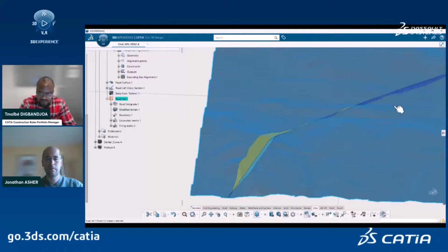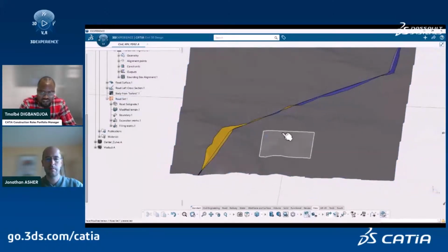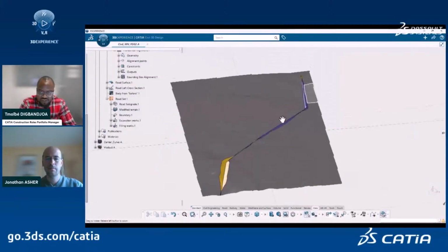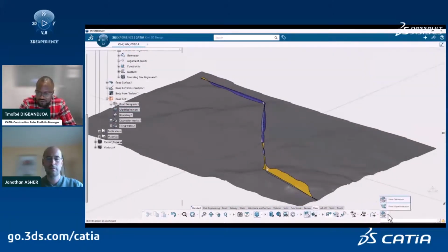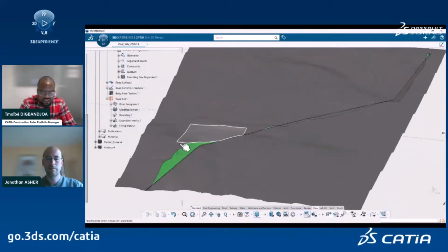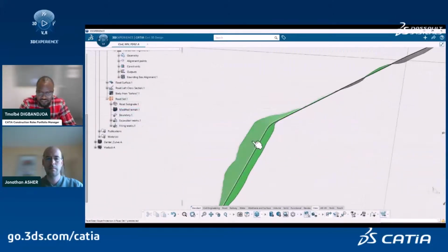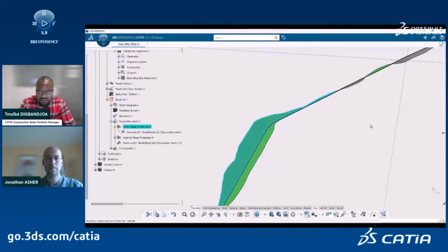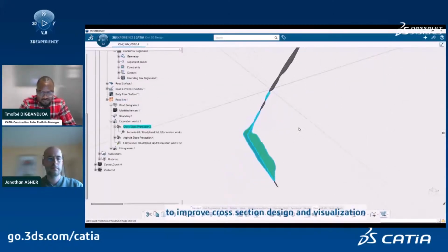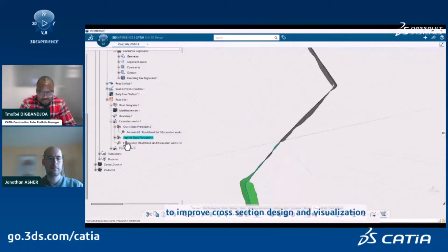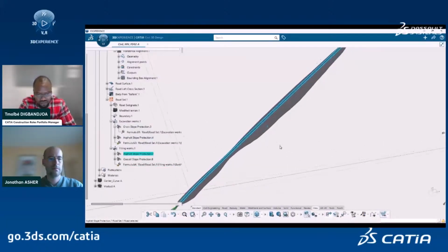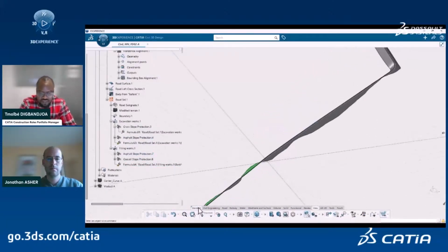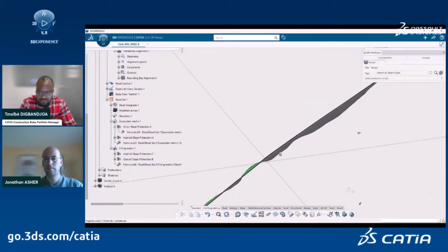So the green part, so now you have the fillings and the excavation volume displayed in yellow and blue. And with the new command, we can show the slope protection materials, and now you can see that we have some grass, asphalt, and geocell. And also we can retrieve the quantity, the area of this slope protection using the beam attribute command. Like this.